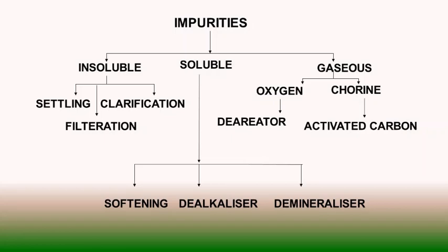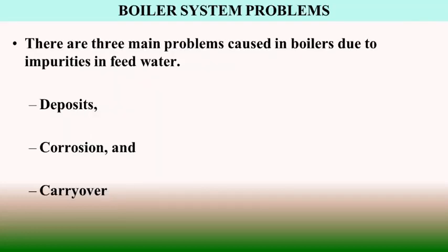Now, the purity requirement of any feedwater system depends on how much feedwater is used as well as what the particular boiler design provides in terms of pressure, heat transfer rate and temperature at which the boiler is operating. And naturally you have to see that purity is maintained according to the desired OEM reference. If the feedwater does not meet these requirements, we must pre-treat the water to remove the impurities.